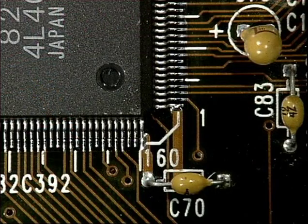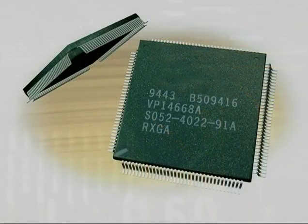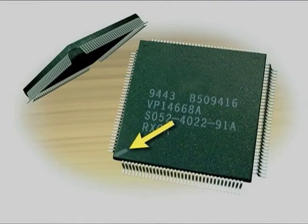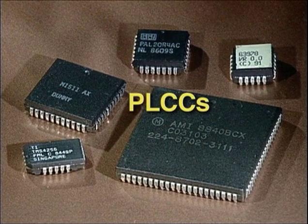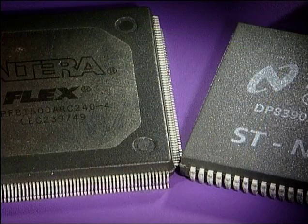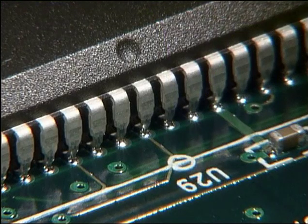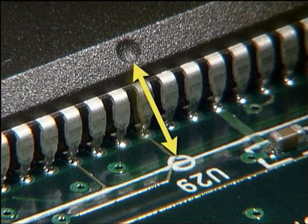Orientation for QFPs is indicated by a dot or a beveled edge over the number 1 lead. Sometimes there may be a chamfered corner or a stripe for pin 1 orientation. Now let's look at PLCCs. PLCCs are also a popular large-scale IC package style. They can have up to 100 J leads on each of the 4 sides. Notice that J leads are not spaced as closely together as the gull wing leads on fine-pitch QFPs. Orientation markings for PLCCs are not the same as for QFPs. A center dot indicates pin 1.